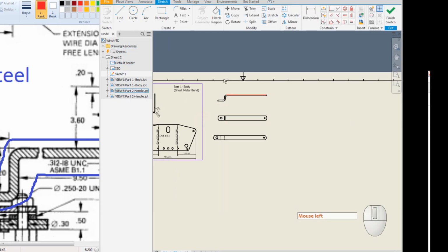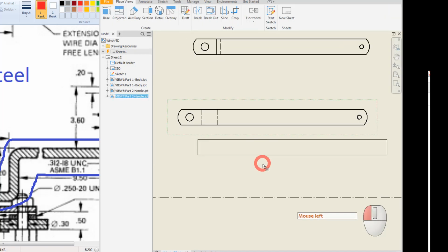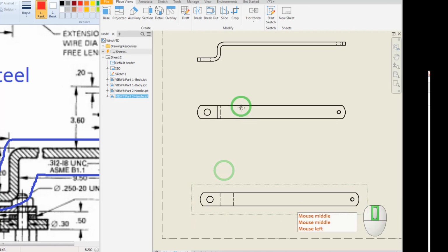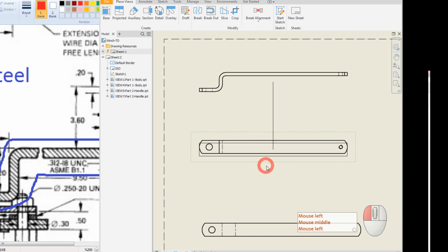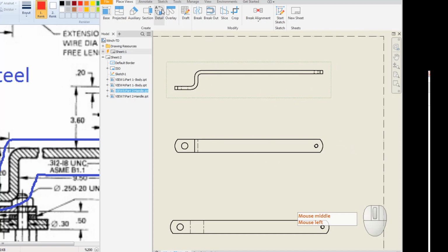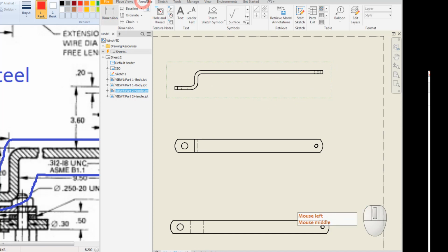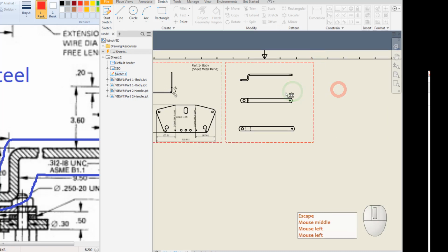I will extend with double click the sketch attached to the page here and draw the borders of our handle technical drawing. Finish my sketch. Here what I'm going to do is I will just retrieve first. I will retrieve the dimensions. If you want, you can just make a sectional cut. This time I create a sketch attached to this view.